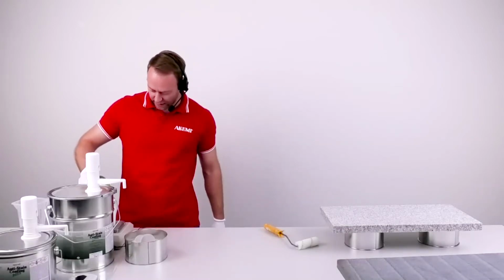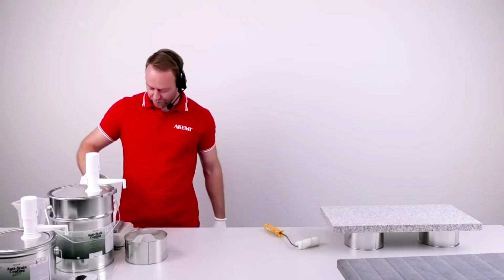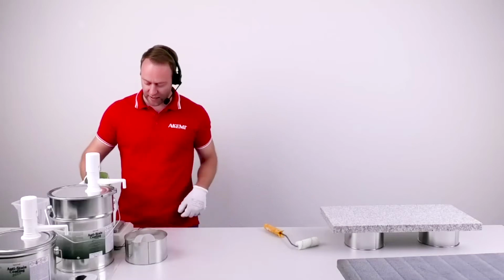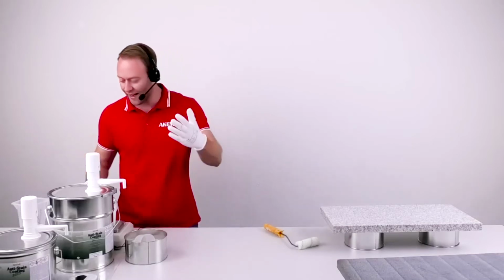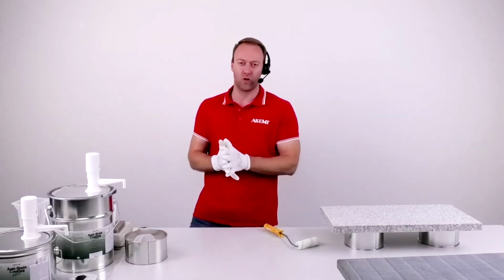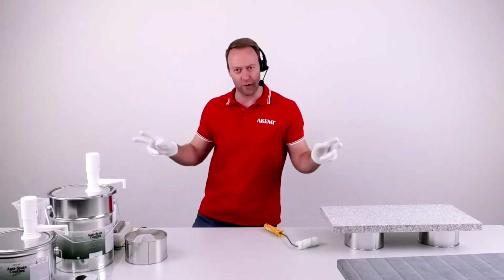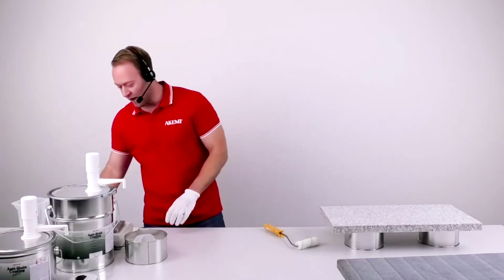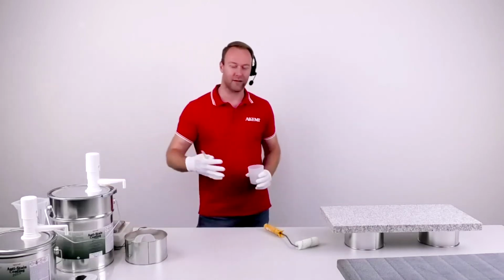The curing time is about 6 to 8 hours. It's already solid, so not sticky anymore. You can start to install it. You can stack it or store it, and installation will be after 16 to 20 hours at 20 degrees. Usually when it's warmer, it gets much faster.